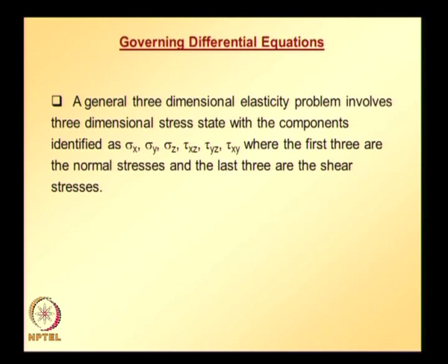A general 3-dimensional elasticity problem involves a 3-dimensional stress state with components identified as sigma x, sigma y, sigma z, tau xz, tau yz, tau xy, where the first 3 are normal components and the last 3 are shear components.